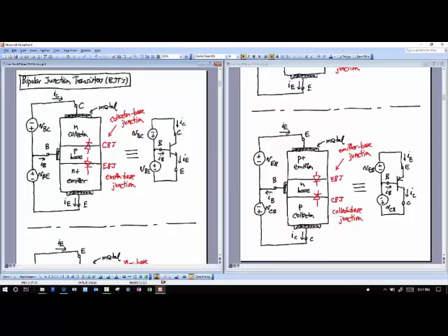That's just the direction of positive current when you actually use the transistor. So usually with devices, the convention is you take the currents going into the terminals. Usually that's what you do, but when you're working with a transistor, because currents always flow down, the way this is really going to look is something like this, where you have your transistor. I'm going to have some voltage VCC up here. I'm going to have some resistor. Then I'm going to have my transistor. If it's a PNP, then it's going to be like that. That'll be ground, and I'll put some voltage on my base.